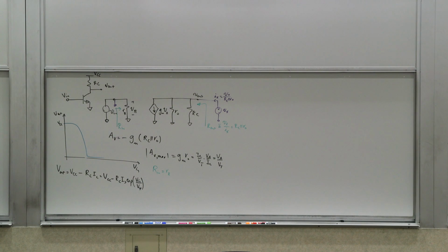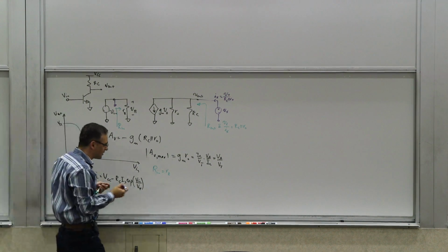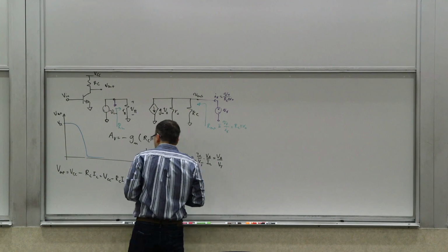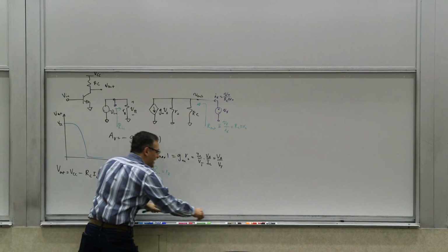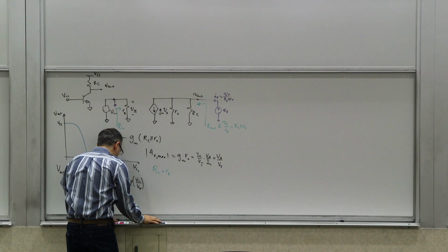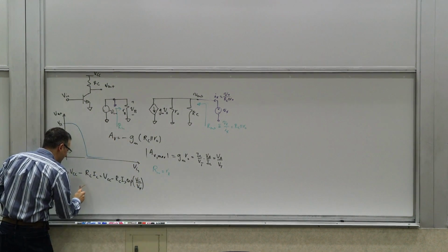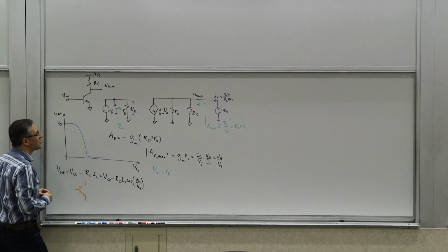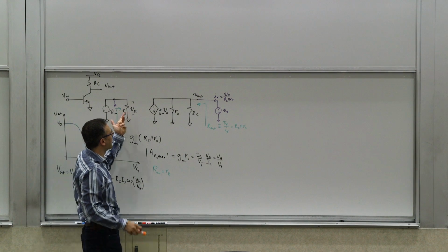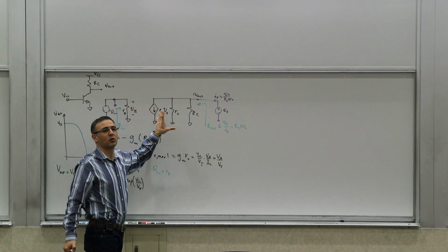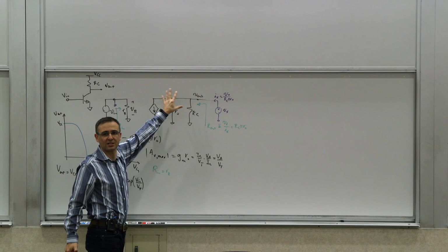Now, as we go forward, we want to also develop some sort of an intuition about the devices, transistors in general. So for example, this is some sort of a rough way of thinking about things, but it's useful to start thinking about it that way because we'll refer to it. If you have a transistor, really what these resistors that you're talking about are really Thevenin or Norton equivalents of what is inside everything else.